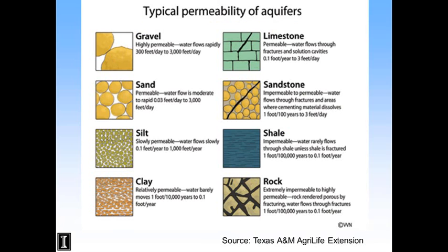Okay, so the other important characteristic is permeability. An unconsolidated material, which again is sand, silt, and clays sitting on top of bedrock, in the northern half of the country has usually been deposited by glacial events. So a glacier came along, 1,000 feet high, and scraped up a lot of material 1 million years ago, for instance, and as it melts, it deposits sand and gravel first because they're the heaviest particles, and then later clays and silts, and that becomes the new soil surface.